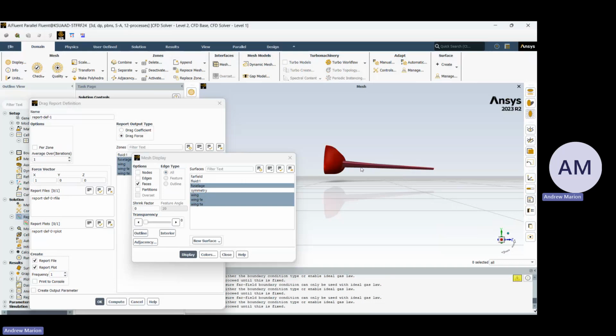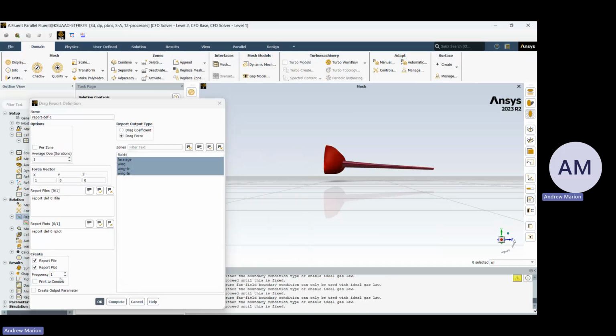If you want to minimize drag, you want to make your cross-sectional area into the air as small as possible. That's why fighter aircraft have highly swept wings. They minimize the amount of drag they experience because they're trying to fly at higher speeds. A commercial aircraft is only slightly swept because they fly in the transonic regime. But we don't need to do that now. We'll just do drag force.